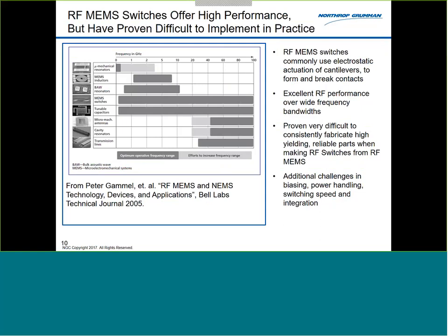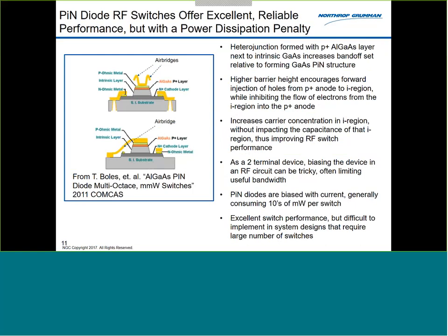And so that has been the guiding light behind all this analysis and project. Of course, there is a solid-state device that works as well as MEMS, and that's the pin diodes, but there are all kinds of caveats associated with the pin diode. Number one is the power consumption. There are a number of applications that couldn't tolerate that, where you're looking at approximately 10 milliwatts per pin diode of just DC power consumption.